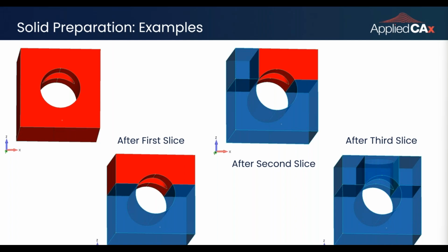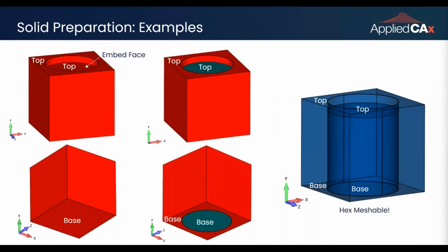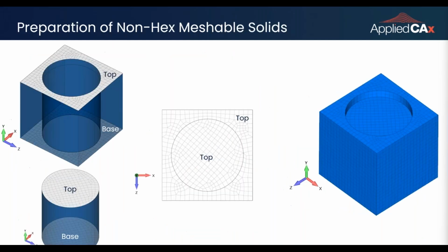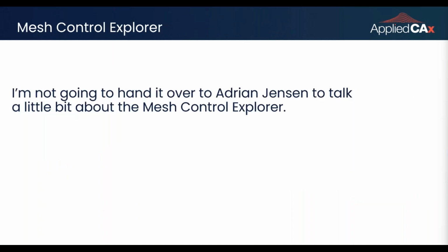So again, these will just be up on the web to show you where I sliced. Here I removed that parting line on the surface before I stopped. Here you can see I've just identified the various components of these parts. And again, here I'm just showing, you can see that the base and the top meshes are identical. They line up, and then when you put them together, they also line up because those surfaces have been matched.